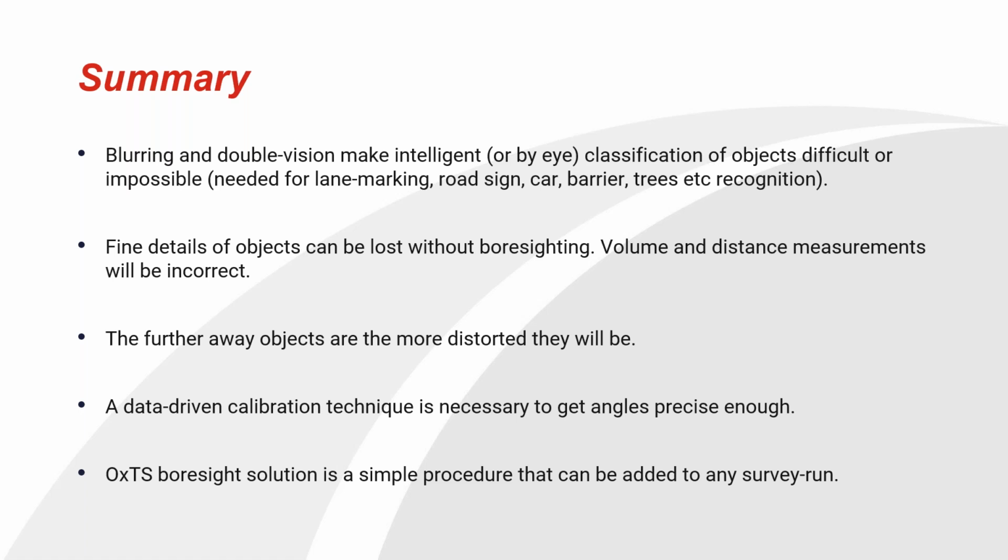You're obviously going to lose any fine details. So if you want to give a customer a pitch, for example, for why they should choose you, you want to give them the best looking point clouds that can be used very easily for different applications. You're going to need to boresight your data. Remember that the further away objects are, the more significant this is, and that a data-driven calibration technique is essentially necessary for you to get the precision that you need.